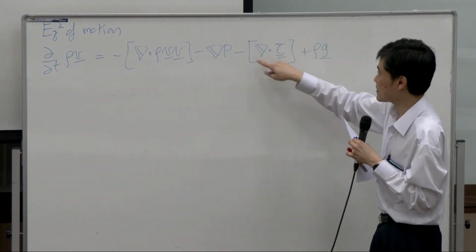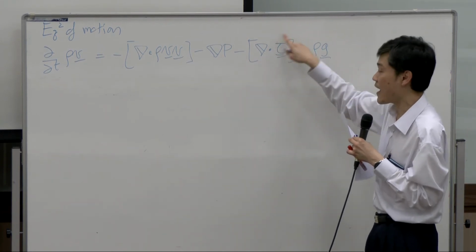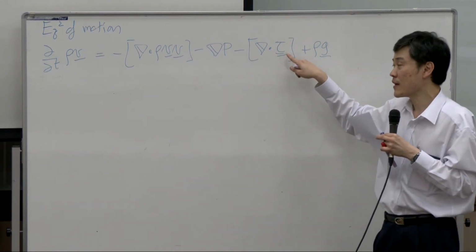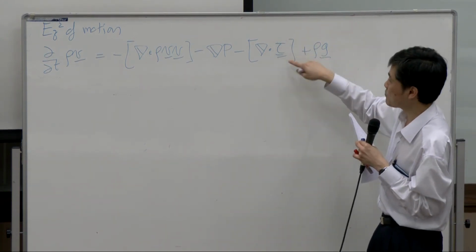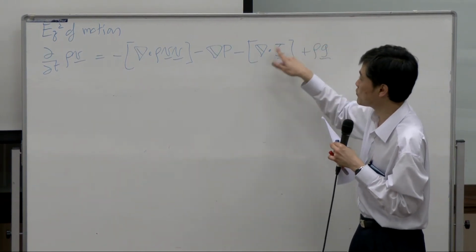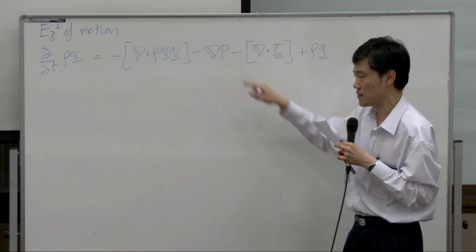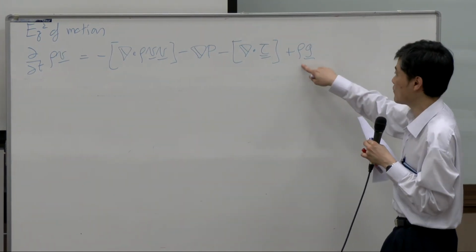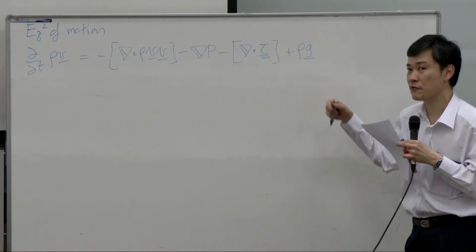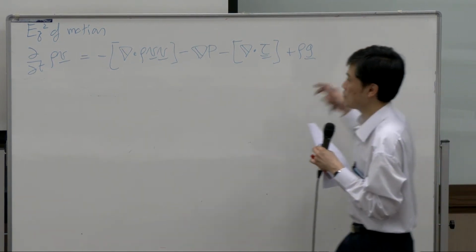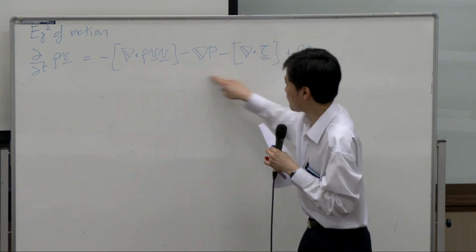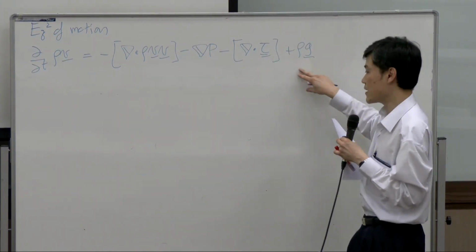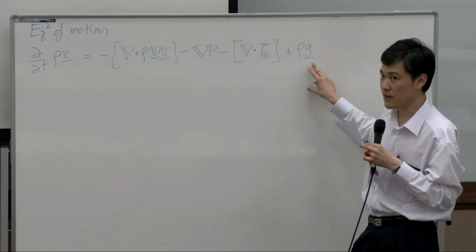This is net flux, minus del dot tau, the momentum flux by means of molecular transport. And molecular transport of momentum contains two terms, tau and pressure. Then there is external force, the gravity force, that creates momentum. So this is basically the net rate of flux going in and out, plus generation of momentum by means of external force.